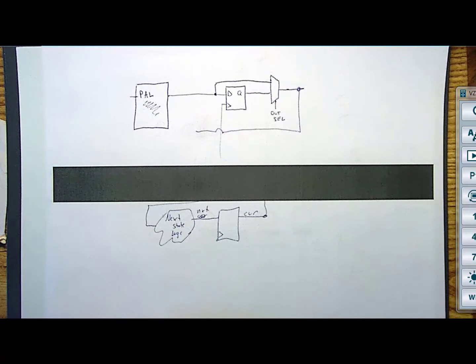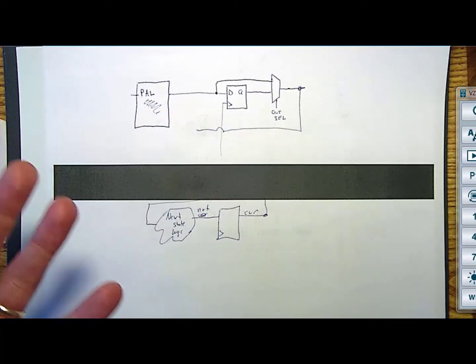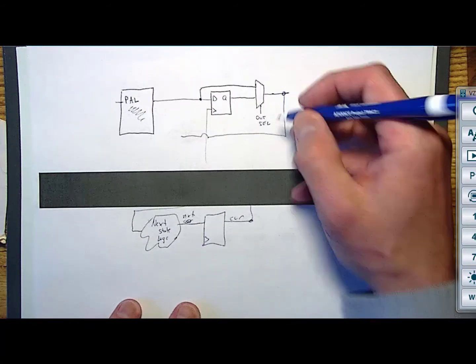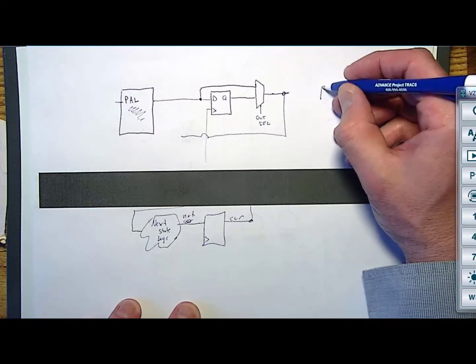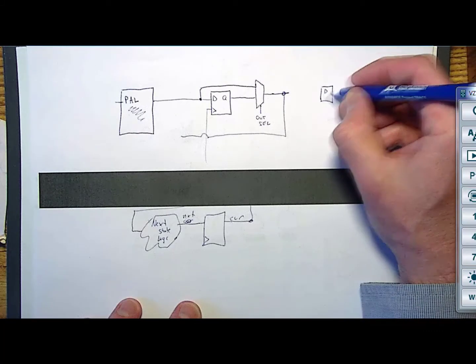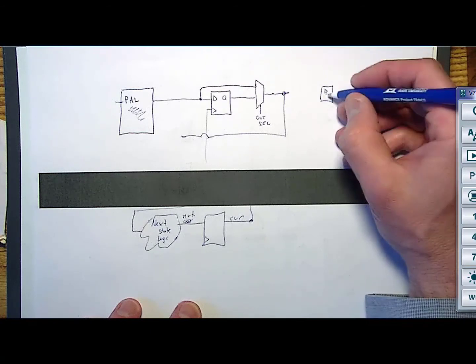And then they said, okay, if you're going to bring your output back, that's only one bit of the current state code. You've got to be able to bring other ones back also. So what they ended up doing is they said, okay, let's put an output transceiver. Remember the transceiver that we've looked at, where you have a buffer that's driving it, but it has to be tri-state and all this sort of stuff, and then you have an input.